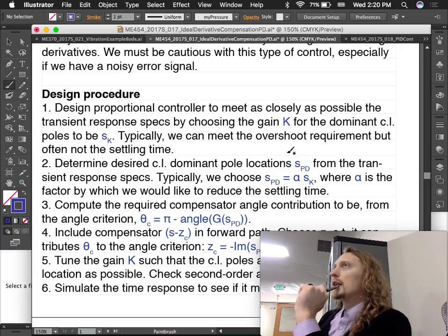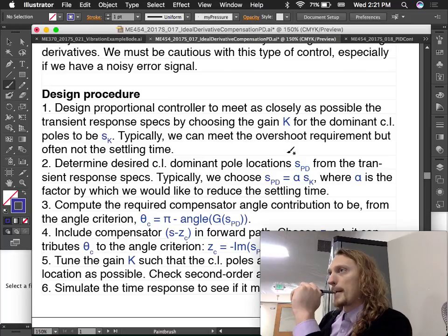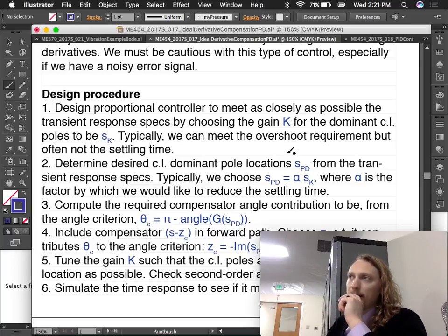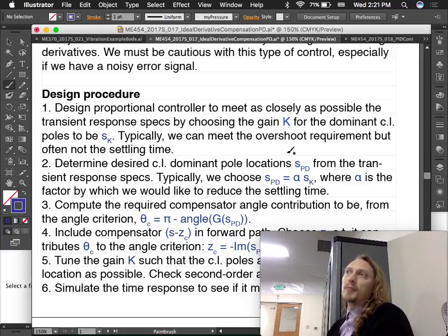So not so much that, no. I was going to say, because you're on that ray of constant damping, and if you're on that ray, it sets your natural frequency, the length of that ray, right? You're selecting it. If you're always selecting along that ray, you'll get the right damping.